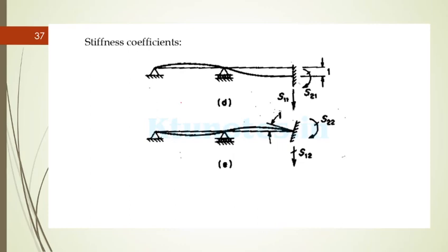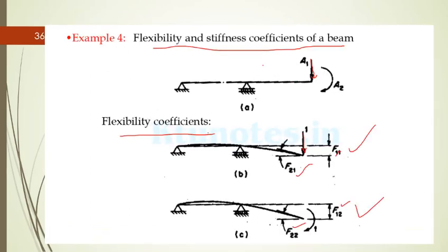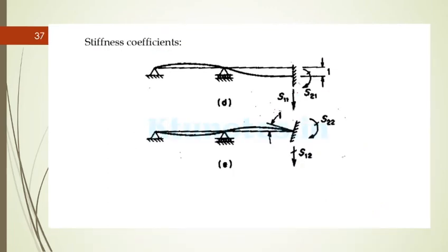To find the stiffness coefficient, if you remember, you should apply the vertical displacement of 1 and also the rotation should be 0. So this condition is possible for sinking supports like this, that is the rotation is actually 0 and the deflection is equal to 1. Okay, and for the second case you should arrest the vertical deflection. You should give only a unit rotation which will look like this. So there is no vertical movement, there will be only unit rotation. This unit displacement 1 and the corresponding forces or actions are known as the stiffness coefficients S11, S21, S12 and S22.